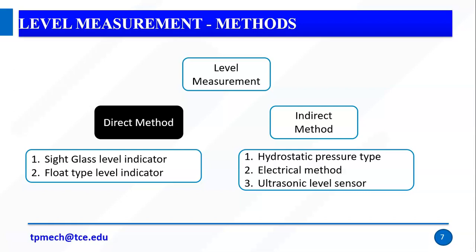What we mean by direct and indirect is that direct shows the exact value directly. For the level, there will be a scale, and you can tell just by looking at the scale. One example is a dam: to check the water level they have a scale on the surface wall. By looking at the scale we say, for example, that Mettur has 110 TMC of water. The scales are directly pasted or attached on the dam wall, and the water level readings are there, so we can measure. This is one of the examples of the direct method.